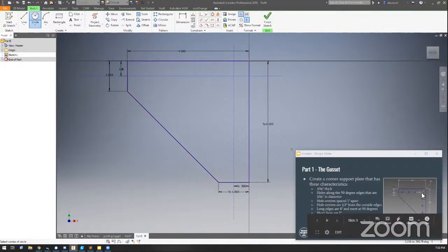So these holes you can see here, the first one is right in this corner. Well, I've got a nice anchor spot that I created when I did these 2 construction lines. So I'm going to go at the center here, use my circle tool, and draw a circle. Okay, they've indicated that this needs to be 3/16 of an inch, and I've done it again. So I still have construction selected. So now I've drawn a construction circle instead of a real circle. I'm going to Control Z that, then do this, and then draw my circle again.